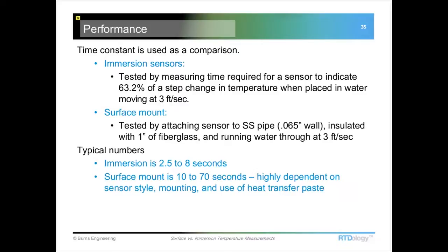For higher temperatures, there are some ceramic things that work well. And if you have a situation where you have a thermal well in a vertical orientation, some sort of oil could be used. Maybe even an antifreeze, like propylene glycol or ethylene glycol. Those are some things that have been used, and they work okay. There's not really any one definitive material. It really depends on how you're going to use it, where it's going to go.